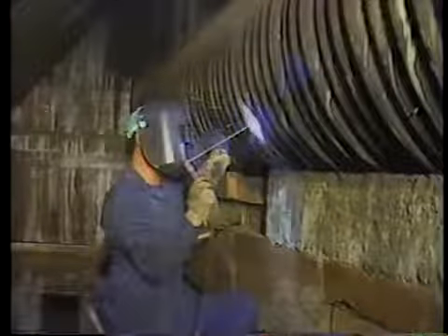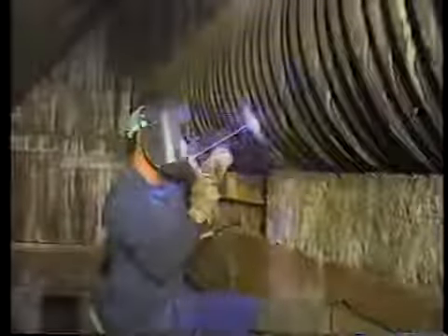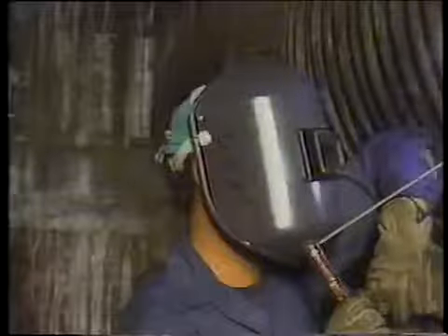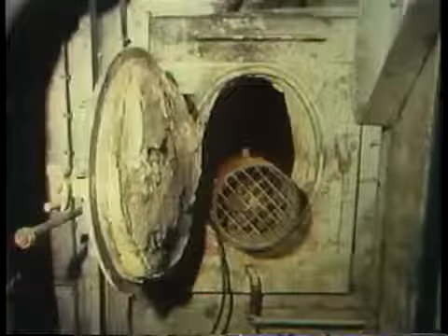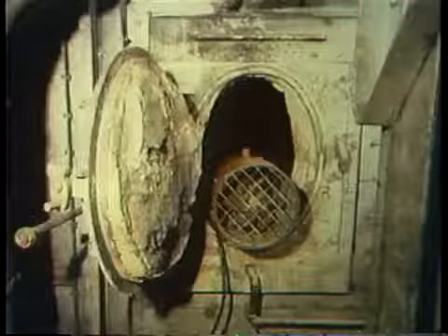There are several precautions that must be taken to protect against hazards caused by welding. First, the welder and his helper must be protected from the electric arc's intense light by welding shields. These shields have special glass lenses that filter this light to keep it from damaging the eyes. Second, the area where the welding is done must be well ventilated because of the harmful fumes produced by welding. In a confined area, it may be necessary to set up a portable fan to get adequate ventilation. Third, the welder must wear gloves and heavy clothing to protect him from sparks and molten metal.